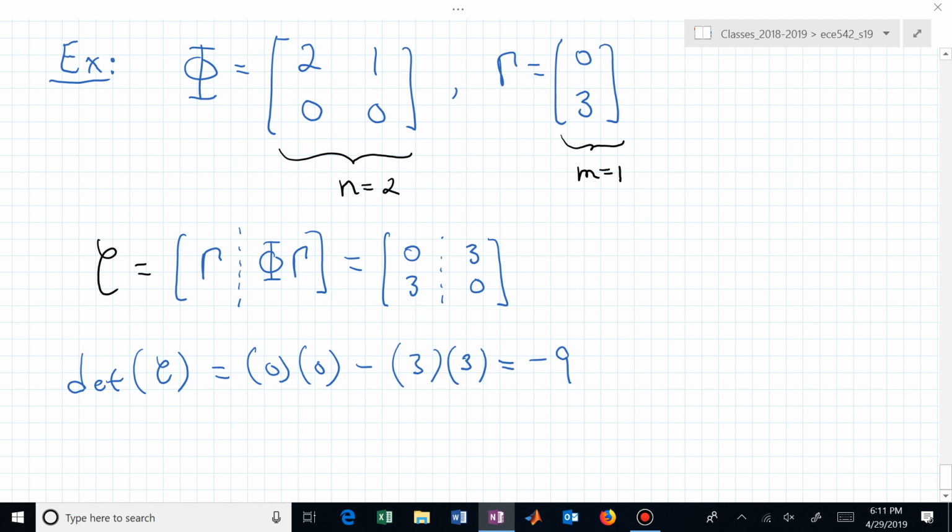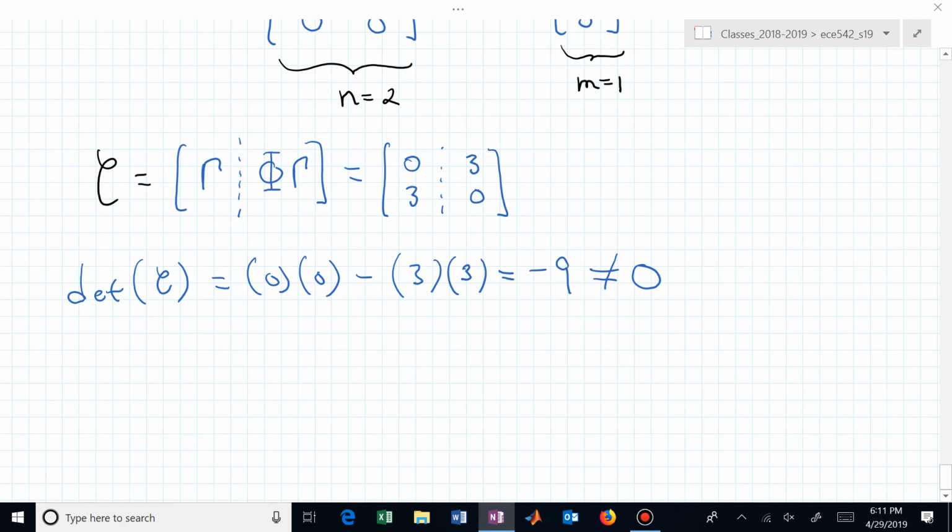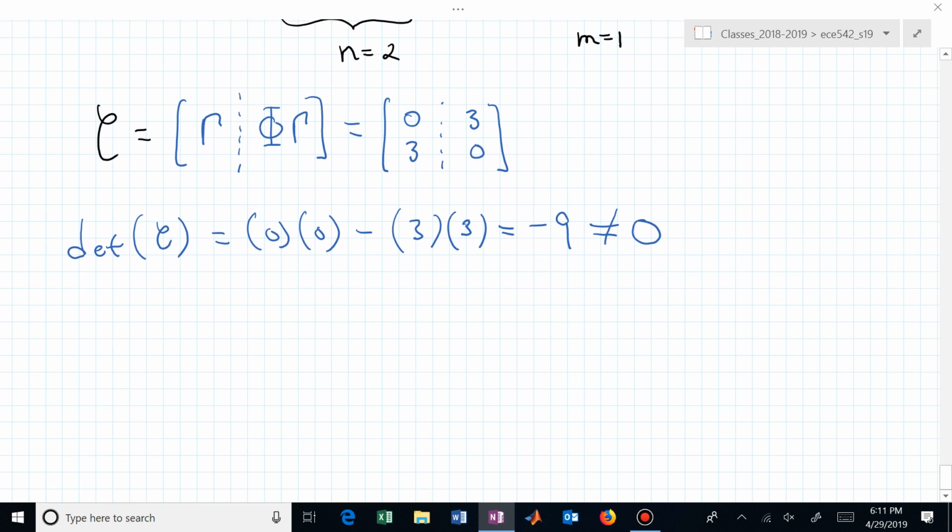That's all you're after. That actually tells you that you have linearly independent rows or columns in this square matrix that you've now found its determinant for. There was no 0 eigenvalue in that set of columns or rows making up that matrix, and in this case then the system is controllable.